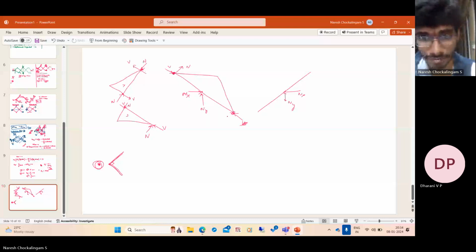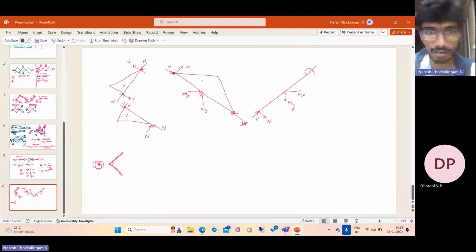Yeah, so this point is connected to this point. So here you again have the normal force becomes the shear force, and shear force becomes the normal force. This side you need to determine depending on this. You just use equilibrium, so you get the two other components. And then you can also draw the moment diagram.